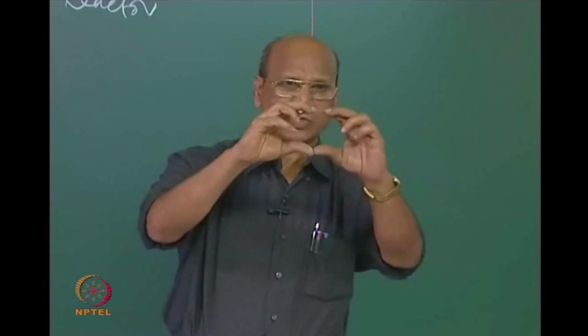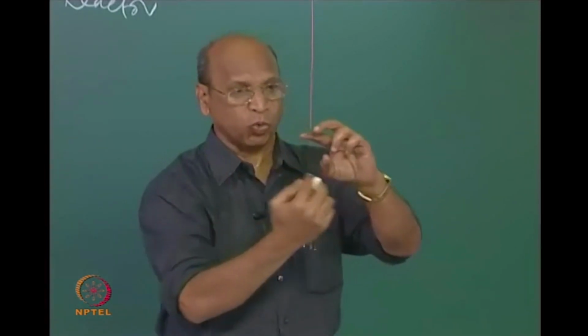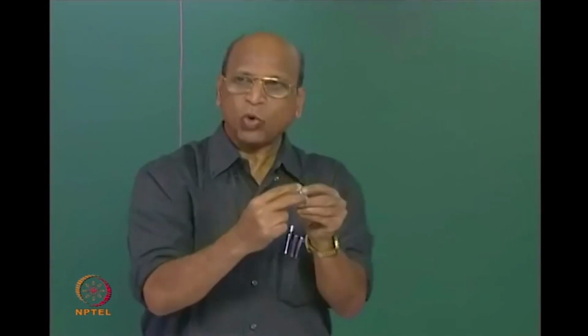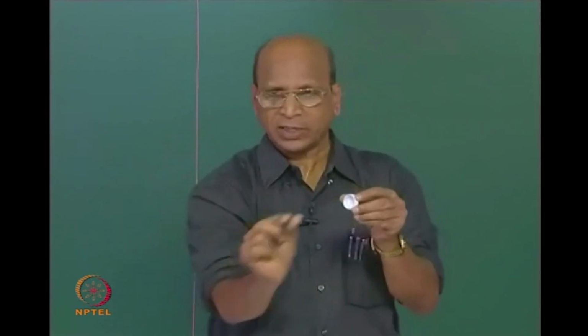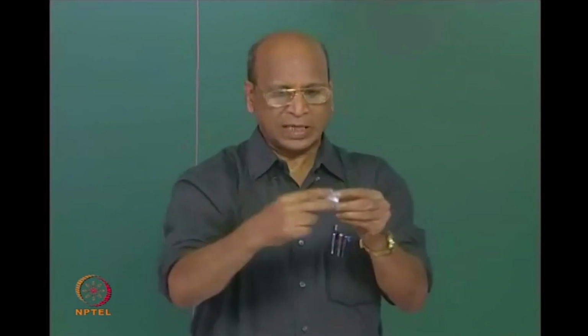When you are joining two metal parts, these two metal parts will have a groove. Here they will have a groove, the other side also has another groove, and in that groove you put that nice circular O-ring, circular in diameter too, and then tighten.